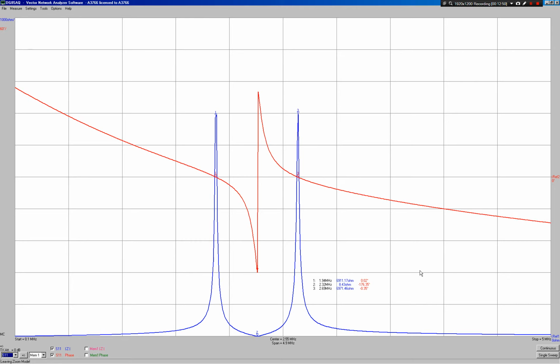If we were using a linear oscillator or a linear amplifier, we'd want to be tuning more on points 1, 3, depending on whether we are tuning at the upper or the lower frequency we want to drive at. Obviously with a spark gap generator or an impulse generator of that sort, we want to have very low impedance. We're tuning towards the lower impedance point, so we get high oscillatory currents or impulse currents in the primary circuit. So that's a nice balance.